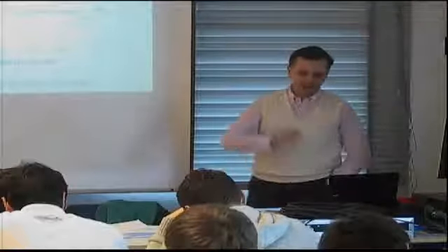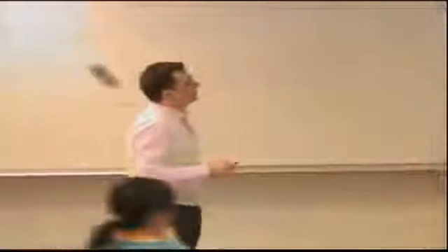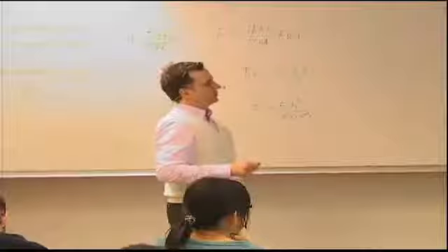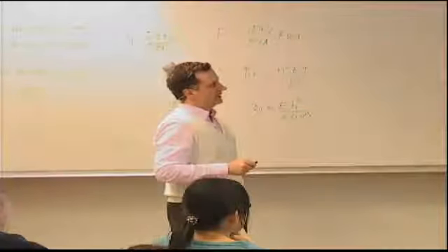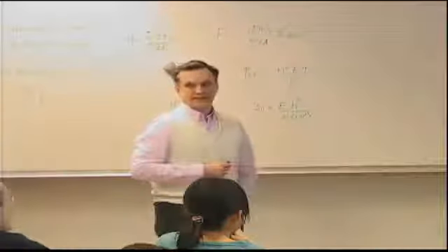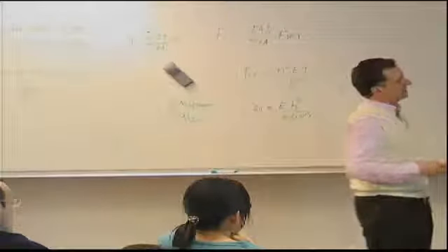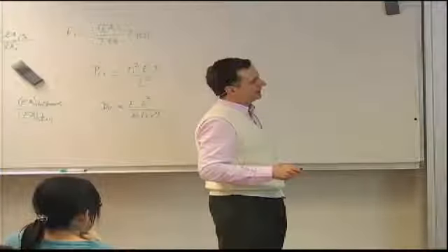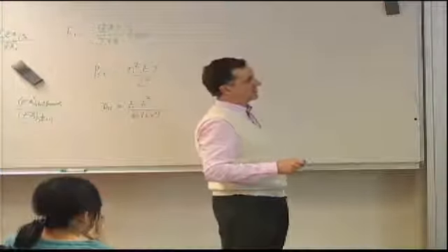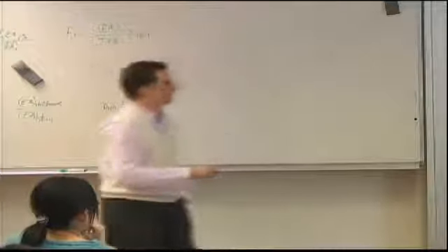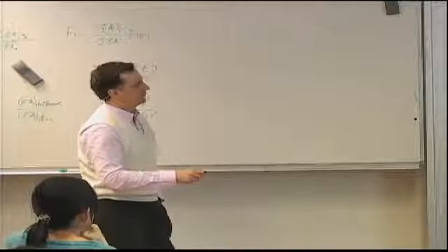If you take the other laminate that we said is a good laminate for this situation, despite the microcracking problems, then the corresponding plot looks like this. Again, the vertical axis is this maximum fastener spacing allowable to avoid inter-rivet buckling. And for any B over T ratio that we might care to use, both curves, the countersunk and the protruding, are above the 20 millimeter spacing of fasteners.